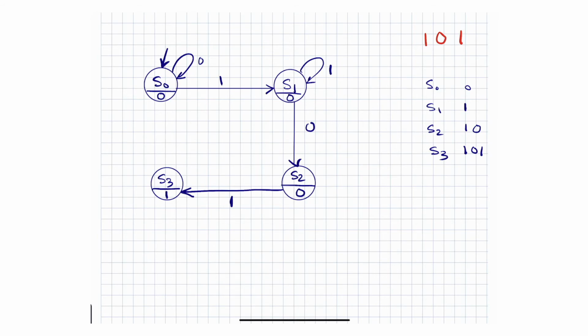And now let's say S2 in here. I've figured out what happens when it's 1. What happens if it's a 0? If it's a 0 followed by 0, well, I think a reset would make sense at that particular point. So I will actually just go in here and do that. I think that makes sense. You go back to the reset state, as if nothing has happened, and then you go from there. That's S2, so we have 2 arrows leaving.